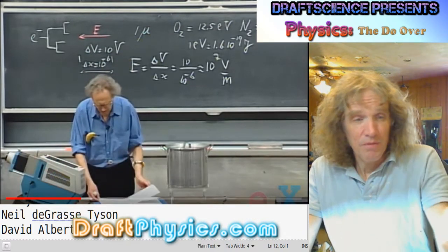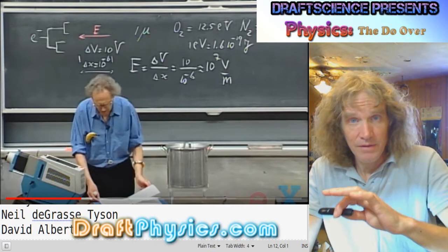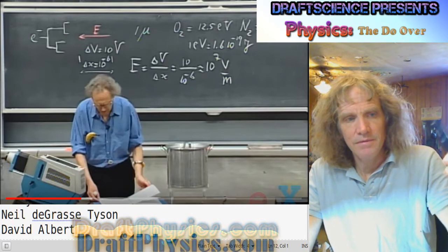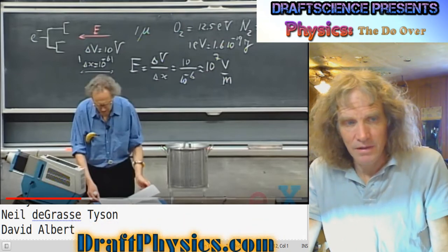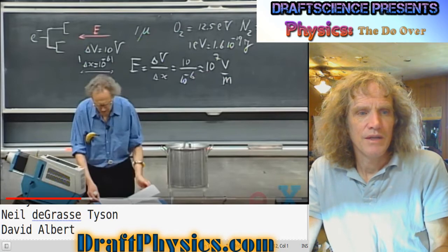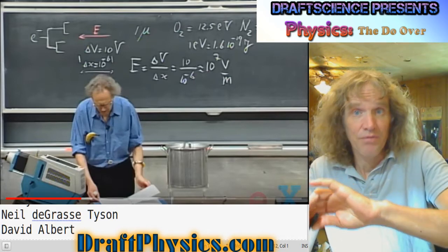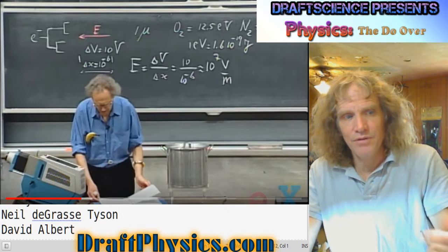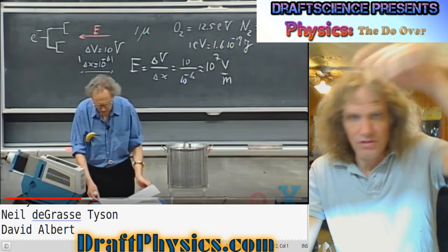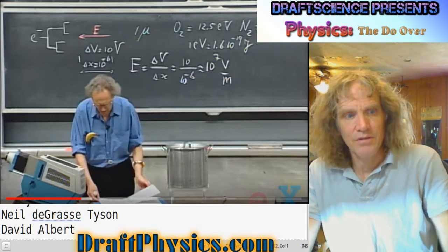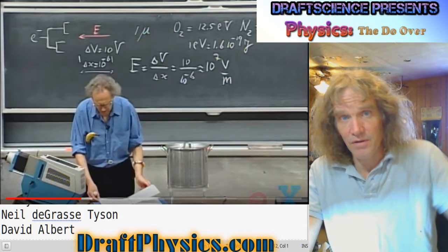So the point is that if you could dry the atmosphere, take the water out of it, you make it a lot less conductive. Fewer molecules also, so that would make it less conductive. So you can increase the amount of voltage before it goes to ground through the atmosphere. The breakdown voltage is specific to our atmosphere. It changes with whatever atmosphere you go into, and space theoretically would have a breakdown voltage of a zillion volts or whatever.